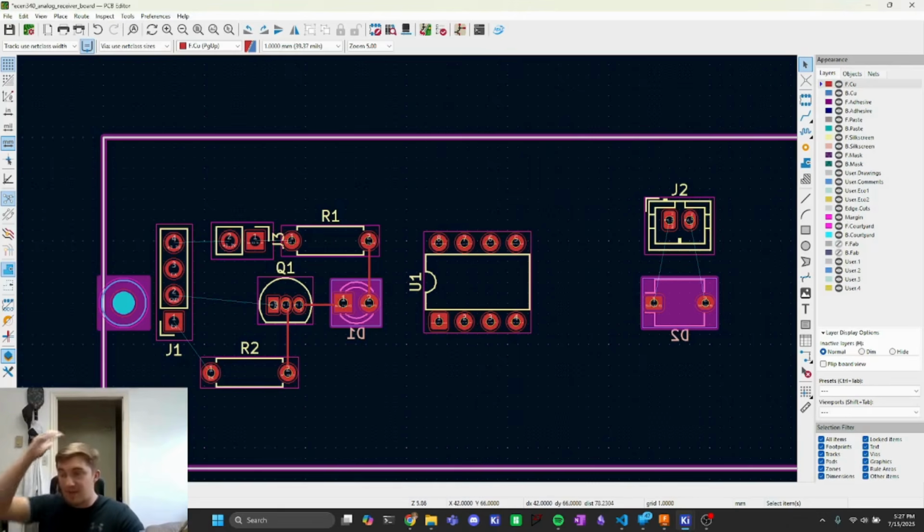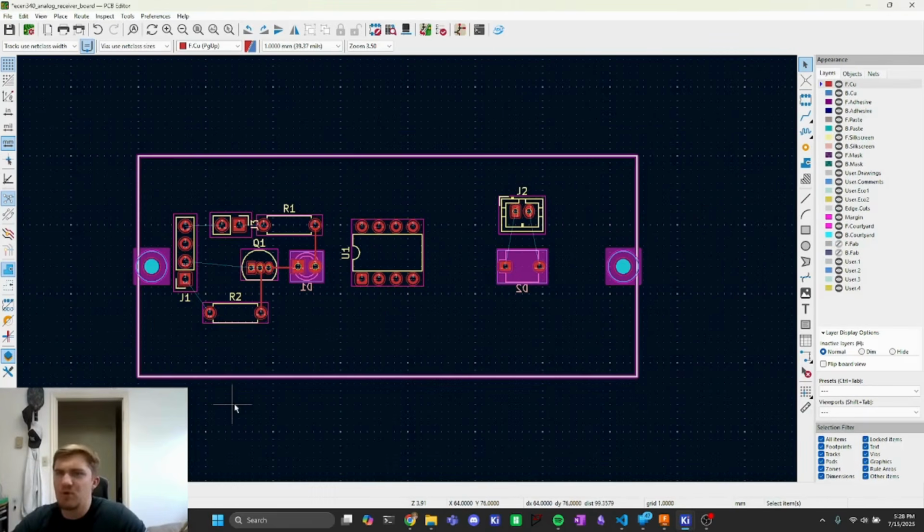2 layers is much better than 1 layer of copper because, like roads and overpasses, it allows you to have more complex connections. You can have intersections without the copper actually intersecting. Having multiple layers will allow us to create power planes. Power planes say, okay, everywhere there isn't a trace or a path in this layer, I will have this connected to a specific net. So, for example, all the copper on the top that's not cut out to become a trace, I will make connected to the 3.3 volt net. And all the bottom copper, we can connect to the ground net.